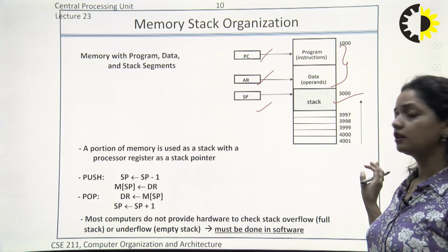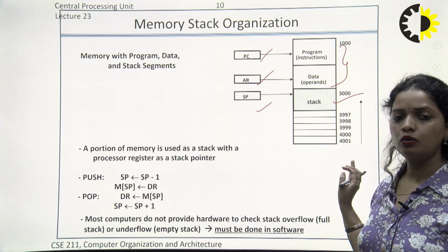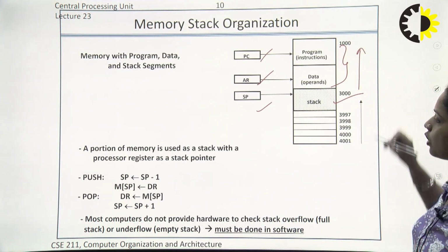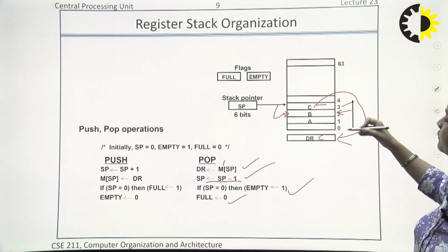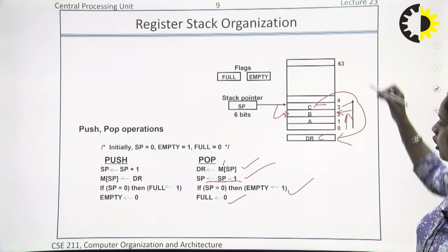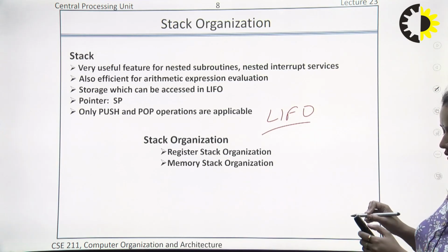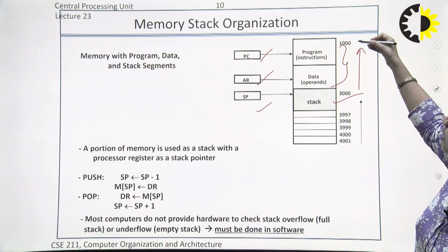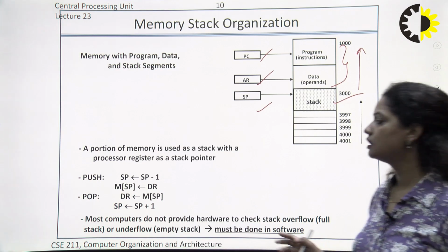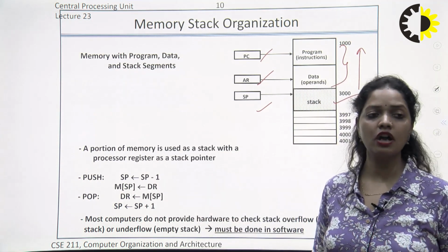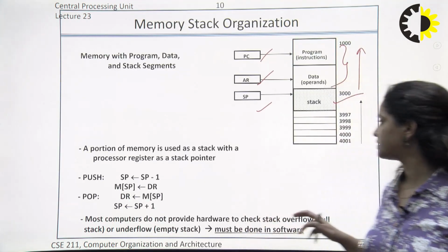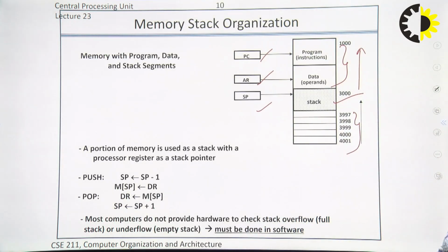So here the major point to look at is that the addresses lie in opposite order compared to the previous one. There we are using ascending order, starting from lowest to top, and here we are using descending order. We can say 1000 is there, ascending in this and descending in this order. So here the operation for push is totally changed. It will now be SP minus 1, and pop will be SP plus 1. Why do so? Because it totally depends upon your address numbers.